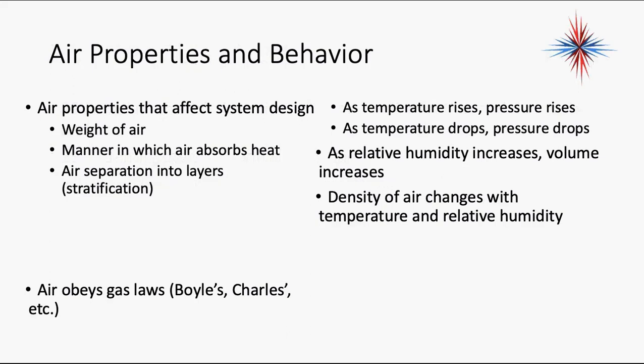So we've already talked about how we have different properties that affect system design. We have the weight of the air. We have the manner in which air absorbs heat. We have air separates into layers. We know air obeys gas laws. As temperature rises, pressure rises. As temperature drops, pressure drops. There is a temperature-pressure relationship in air, which, by the way, is why we never use it to leak check refrigeration systems. We always use nitrogen, okay, because nitrogen doesn't expand and contract. Temperatures and pressures don't change based on temperature.